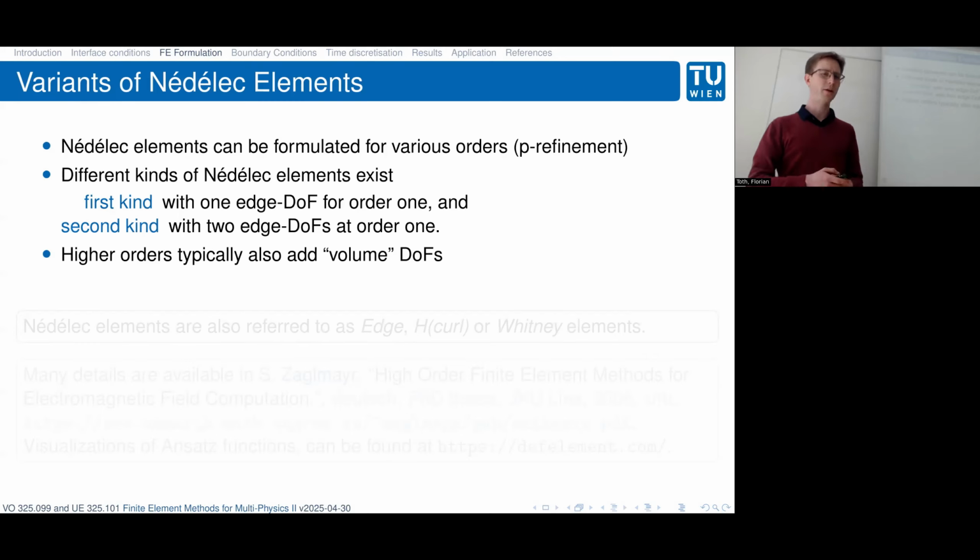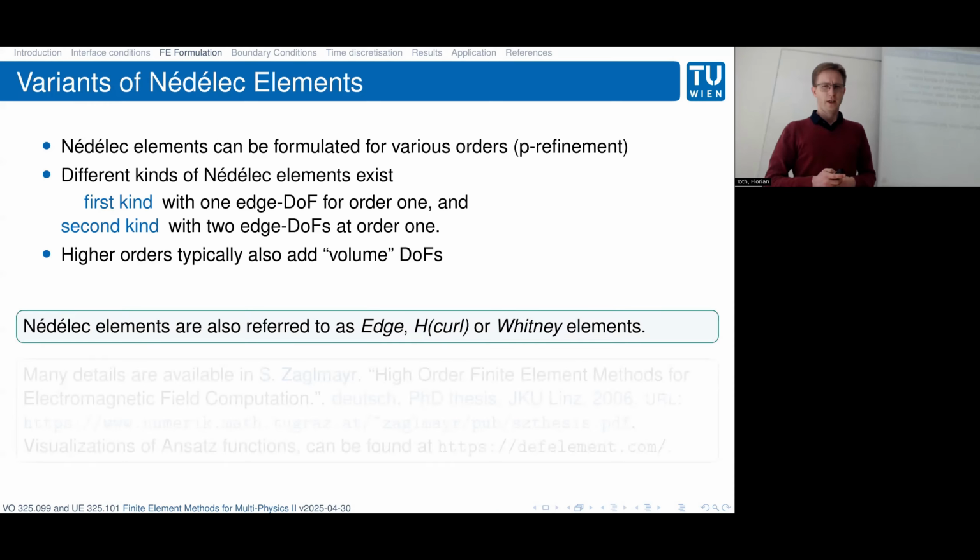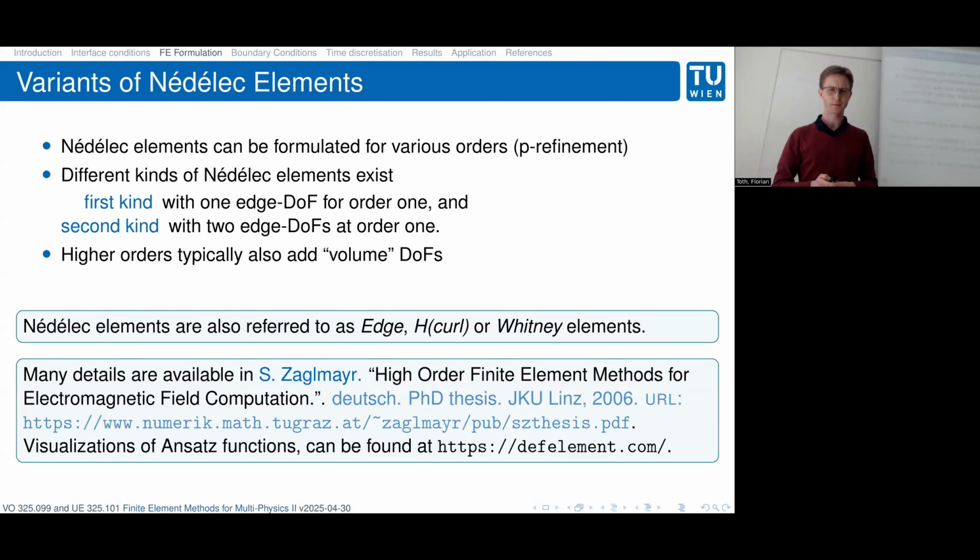And typically higher order Nedelec elements will also contain face or volume degrees of freedom. They are also often called H-curl or Whitney elements, or simply edge elements.